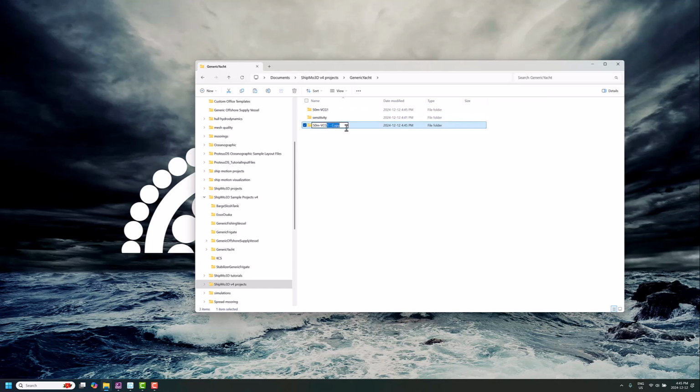We'll call it VCG2. So what I'm going to do is set one with a vertical center of gravity that's 10% lower, and then one that's 10% higher than nominal, and just demonstrate what that looks like when you go through the comfort assessment, and also get a sense of what a realistic variation of that could be from the motion RAOs that are derived from that.